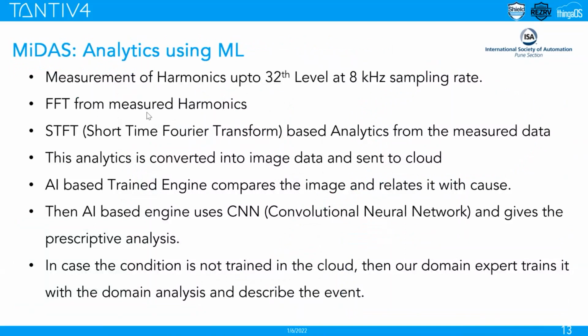So MIDAS is achieving this analytics with a powerful machine learning based engine at the edge and its harmonic measurement capabilities. MIDAS is not only doing the fast Fourier transform to understand the treble frequency when there is some kind of unbalance or misalignment in the rotor, but it also does the STFT, short time Fourier transform, at the edge. As continuous Fourier transform requires big data and high computing, MIDAS does this when it sees some anomaly in the measurement, and sends a complete signature of data measurement for a specific period to the cloud.